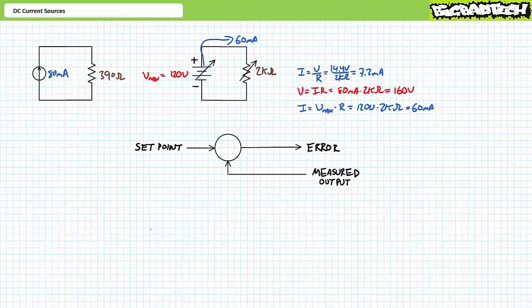Long story short, if you're using a benchtop power supply as a current source, know its operational range and simply operate inside that range. Inside the operational range, the current source should push the required amount of current through whatever you throw at it. Outside the operational range, expect to reach some peak performance, followed by a predictable decline. Okay, I think we've delivered a sufficient introduction to the current source.